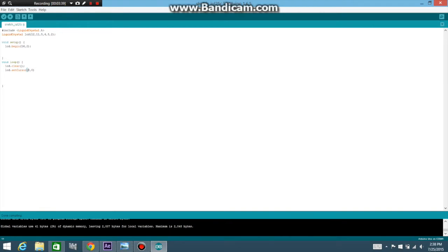One thing that can confuse people is that the first box in the LCD isn't going to be 1, it's going to be 0. So if I wanted to put it on the line under the first one, I would actually have to write it as 1. In this case, I'm going to use 0 because this is the dimension of the first box.